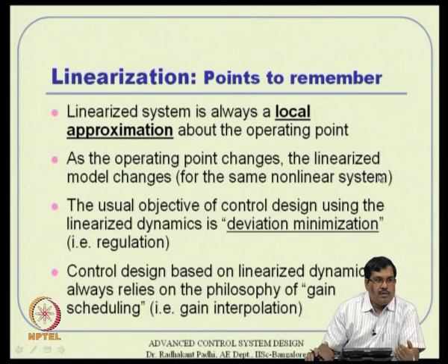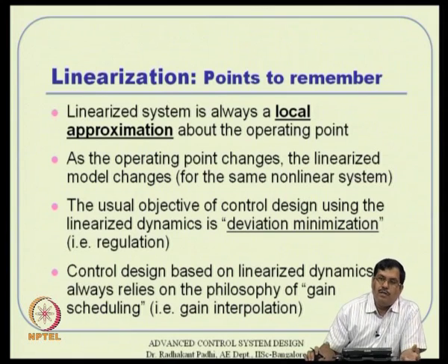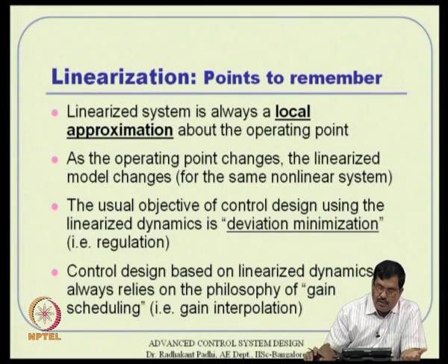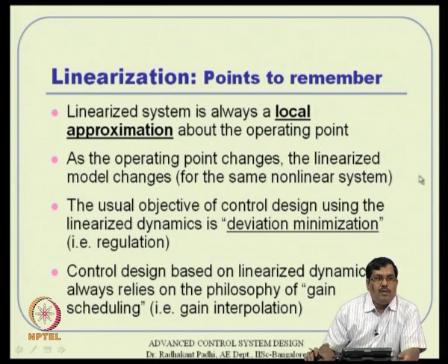So, the Cg variation and mass variation are all embedded into the system dynamics, and will be part of the A and B matrices. So, if you have time varying parameters in the model to begin with, or the system operating points keep on changing anyway, then you have time varying linear systems. Otherwise, you have time invariant linear systems.